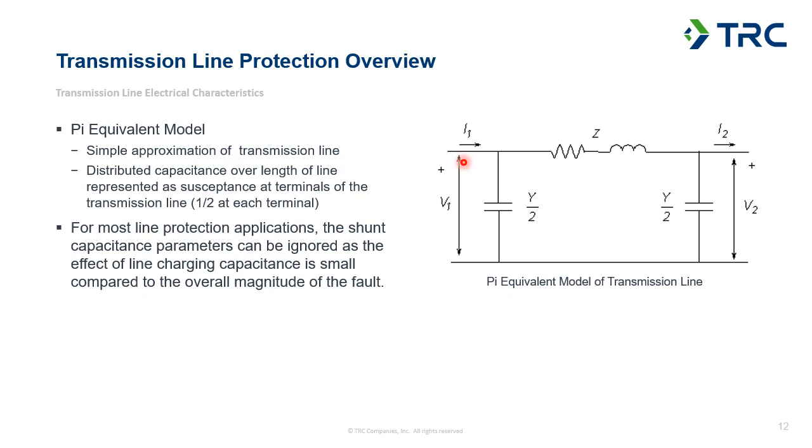And in most applications, that current is so small that it doesn't cause a sensitivity issue with your protection, but in a couple instances that is something that's important to know. So generally, when we model lines, we try to model that even if it's something we're not using. That way, if we do choose to apply one of those types of schemes, we've got the information that we need to adequately model that.